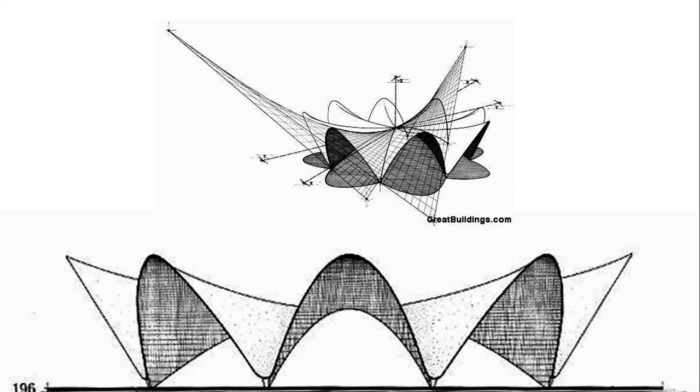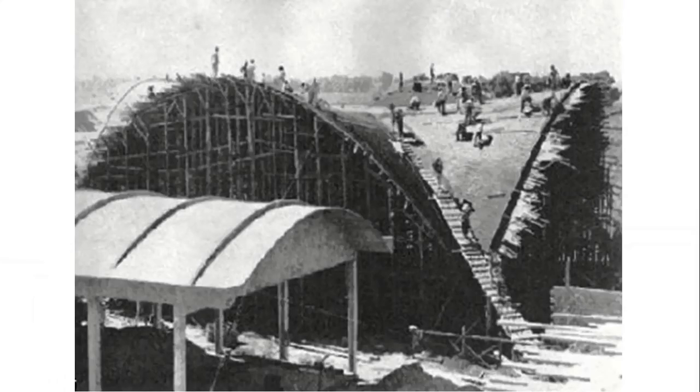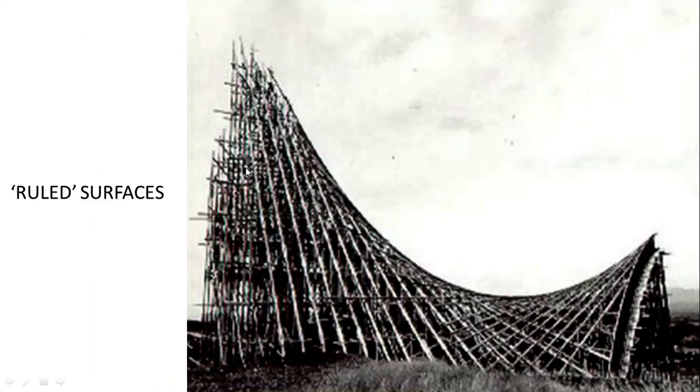This is one of his drawings. Now, again, as I mentioned earlier, you're having to design a huge amount of formwork, aren't you? Here's the mold, the negative structure onto which you're pouring the concrete. Well, of course, in this case it's not very wet concrete, is it? Otherwise it would all slide off. They have to get the mix absolutely right, and there's an awful lot of steel reinforcing cage inside there that you can't see. There's the ruled surface we mentioned earlier.